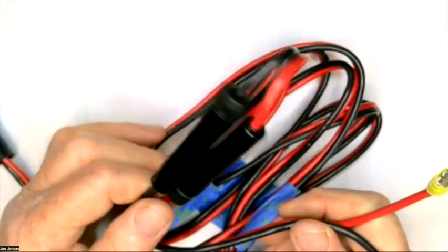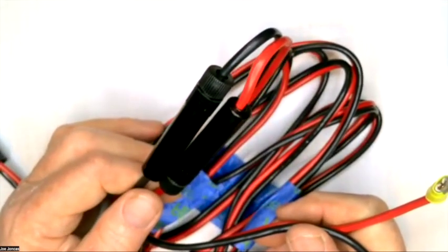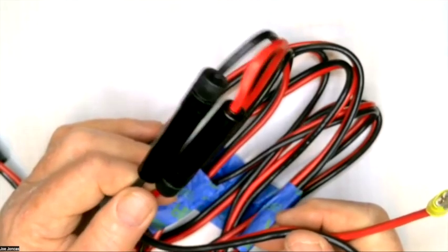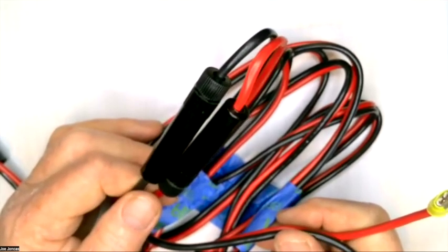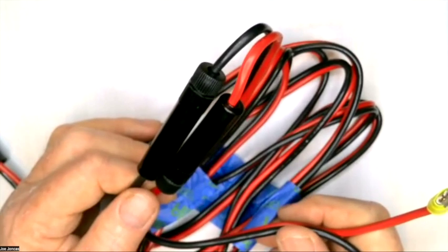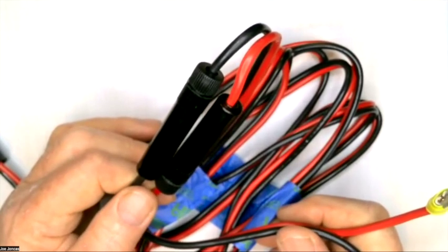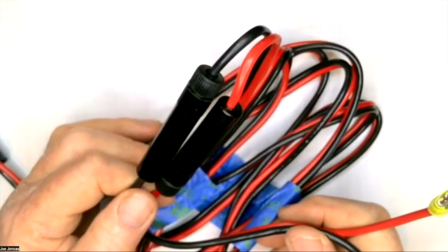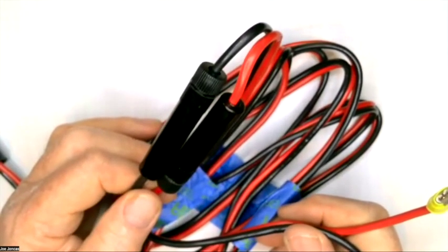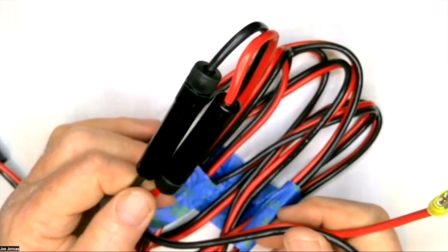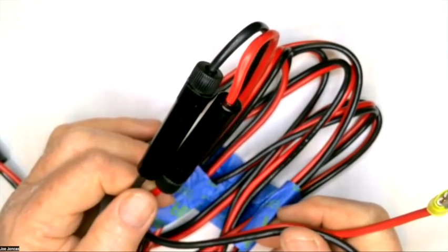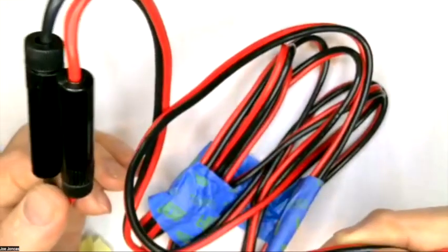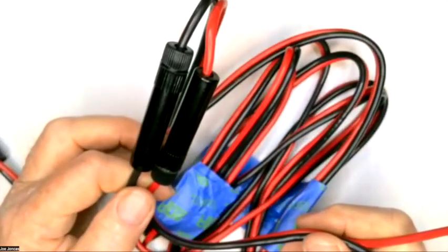I used to work on boats and people would stick a wire in there, hook it up to the battery, and then they'd have a fuse at the other end for the radio or whatever. And they'd burn their boats down because something shorted that cable. And a 12-volt battery for an automobile or a boat or anything else will easily put out 1,000 amps. And when you have that running through a hunk of wire this size,